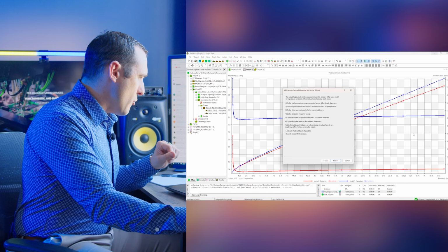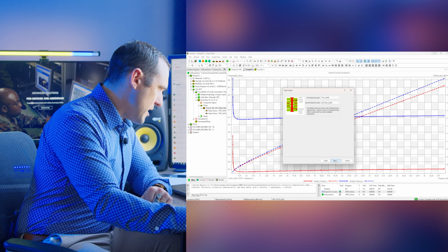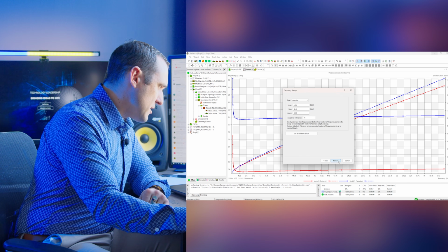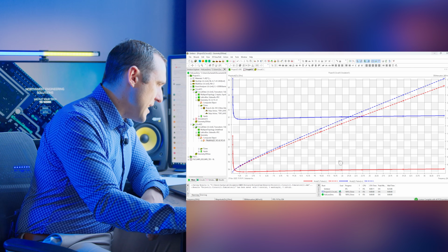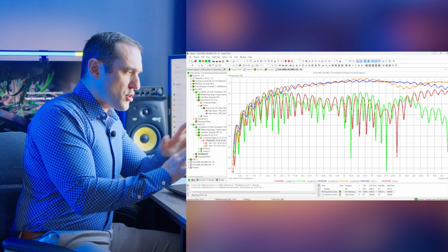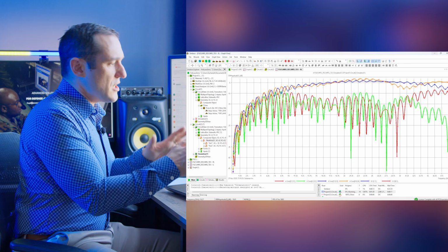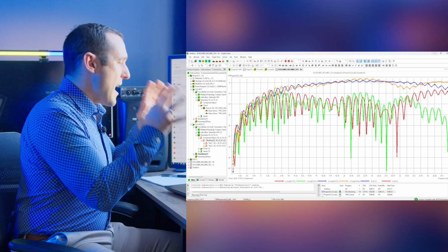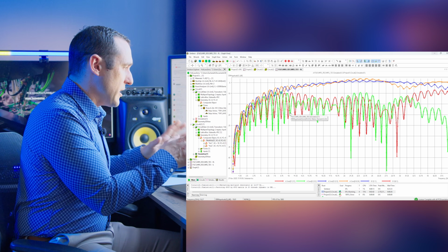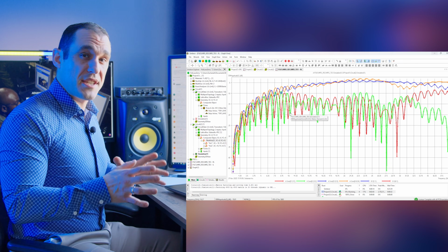So that's extremely useful. I literally just click through a bunch of screens and you can already see some results here for the impedance and the attenuation. We can even do the same thing with vias. Here you can see if I just click on the via wizard, I just click through the screens. You can then see here, eventually we're going to get to a via analysis tool, and it's going to allow us to then simulate what is the S parameters of our via as well as the impedance of our via. So here I just clicked through all the screens on the wizard, but you can already see it's just immediately spit out some results using the built-in fast SI model for a differential via. So that's just a quick example of how easy it is to just load up and start building something with the built-in signal integrity tools on the front end before you start your PCB layout.